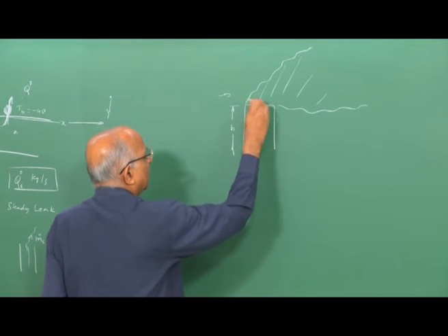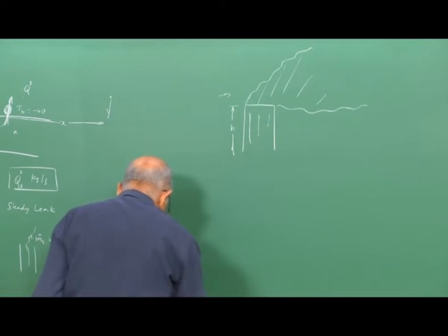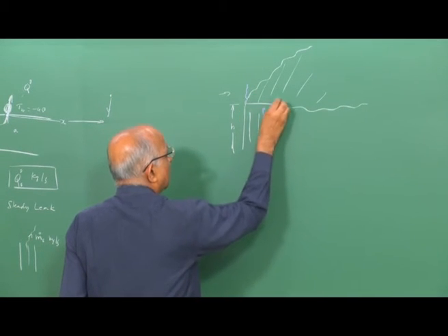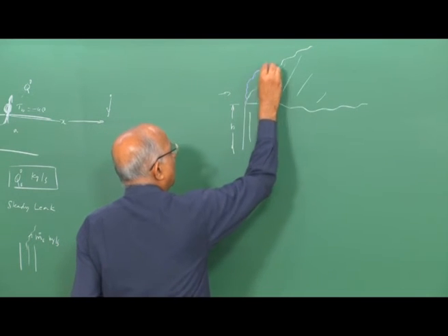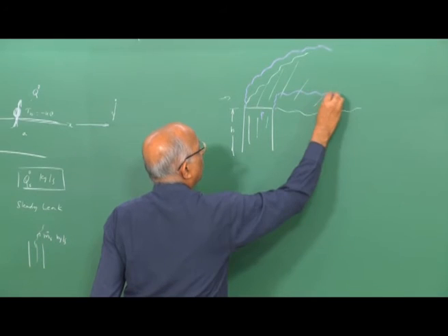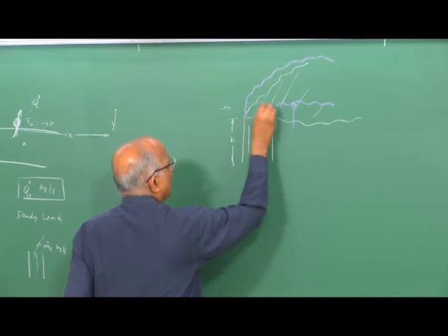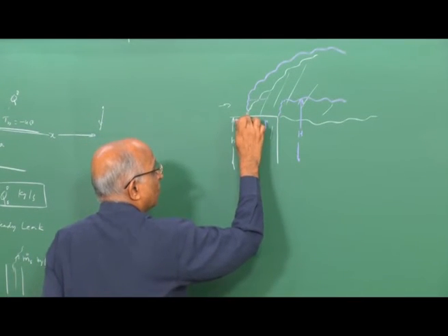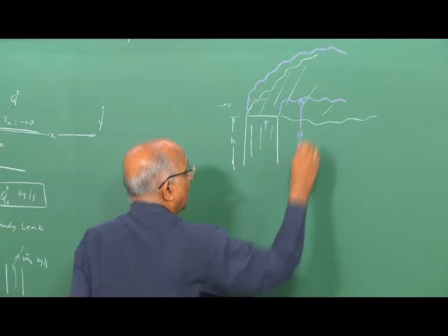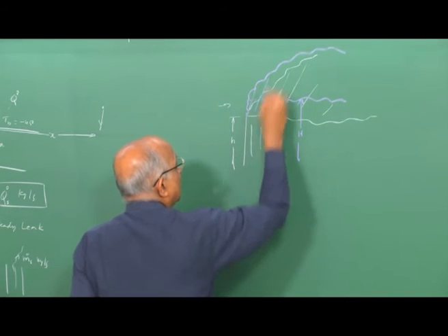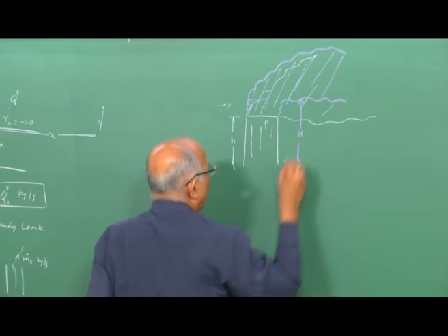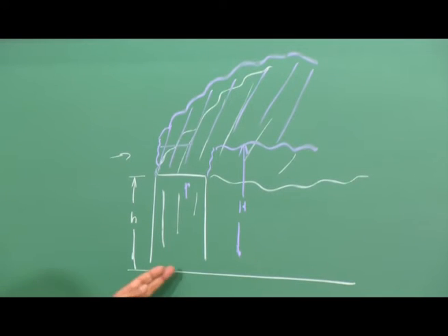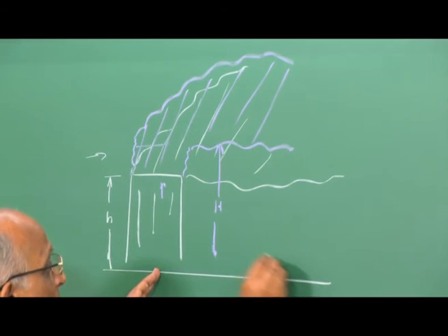Immediately the smoke does not traverse. What happens in practice is, because I have the initial velocity over here, a little bit of smoke comes out like this, and thereafter it begins to traverse over here. Therefore, this is what I call the effective height of the chimney, because the initial momentum pushes the dispersion from this point to the point shown by the violet line over here, and this is the type of dispersion we get.